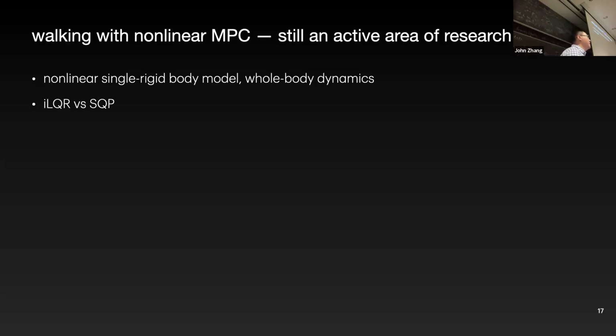In the SQP setting, it is much more general, in the sense that I can add more arbitrary constraints like contact and friction and maybe arbitrary state constraints. But, at least naively, all you get is an open-loop control trajectory at the end, and you don't necessarily get the feedback gains for free. So there's still some discussion of whether you should do iLQR or SQP for these things. And by the way, if you want to add constraints with iLQR, you can also use augmented Lagrangian methods and that sort of thing. So it's still possible to do iLQR with constraints. It's just not something we're doing currently.